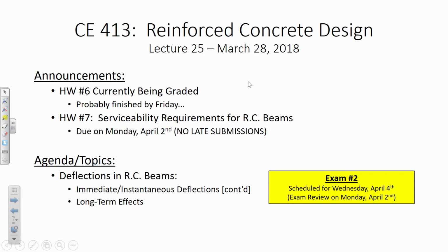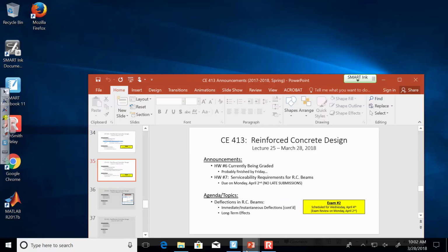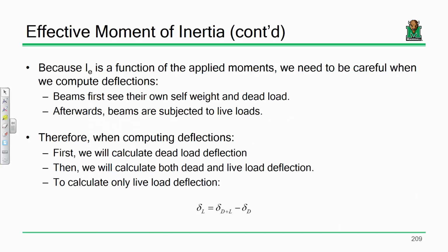Let me recap really quickly to get everybody back into that mindset. Remember, I want everybody to be absolutely clear about this. You cannot compute live load deflections directly in reinforced concrete design. If that was a little fuzzy last time, it's going to make more sense today when we finish our 15A example. You always compute the dead load deflection first, then the deflection due to all of your load, dead load plus live load, and your live load deflection is the difference.